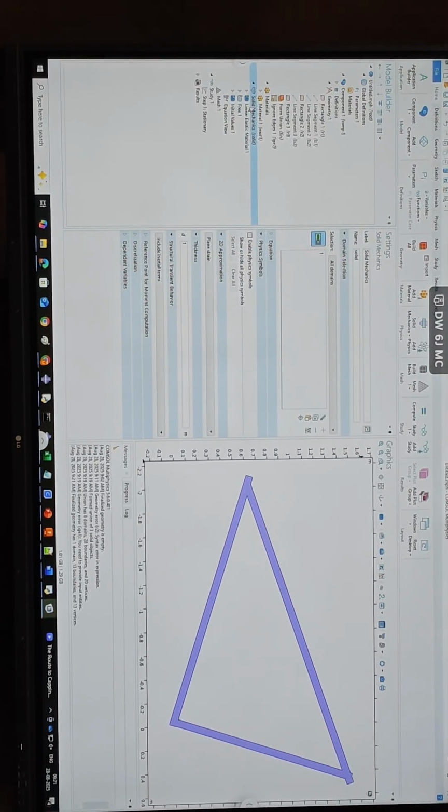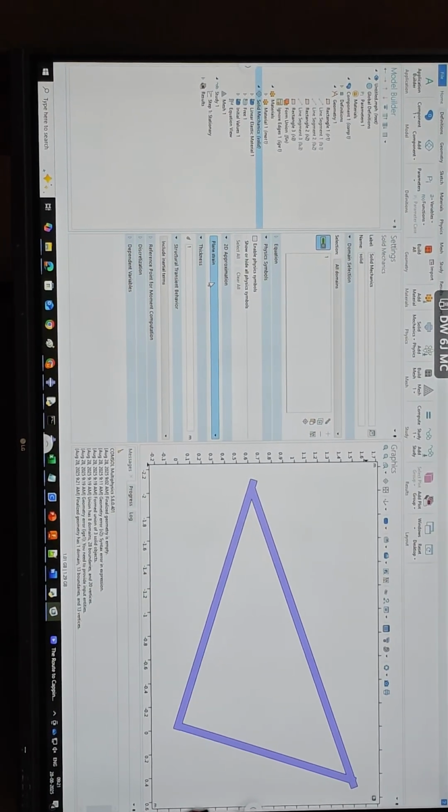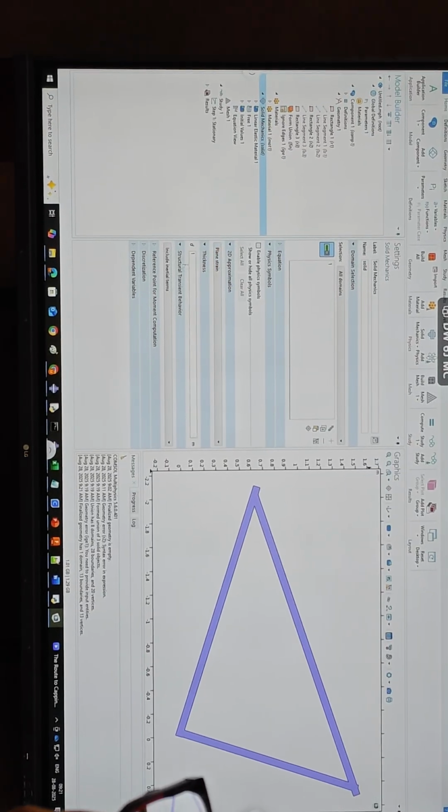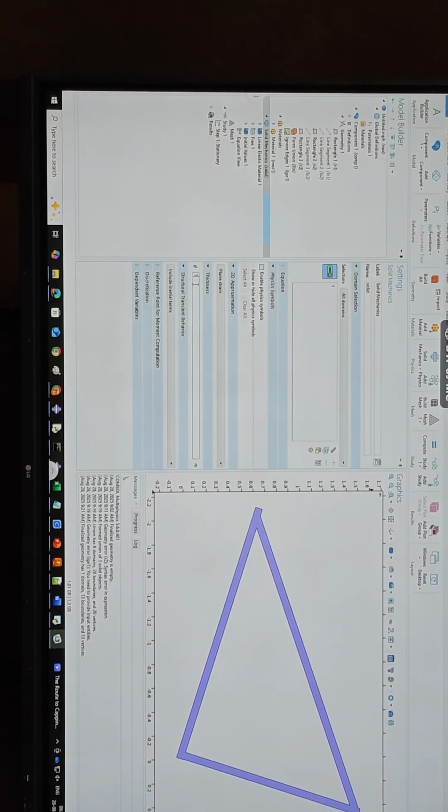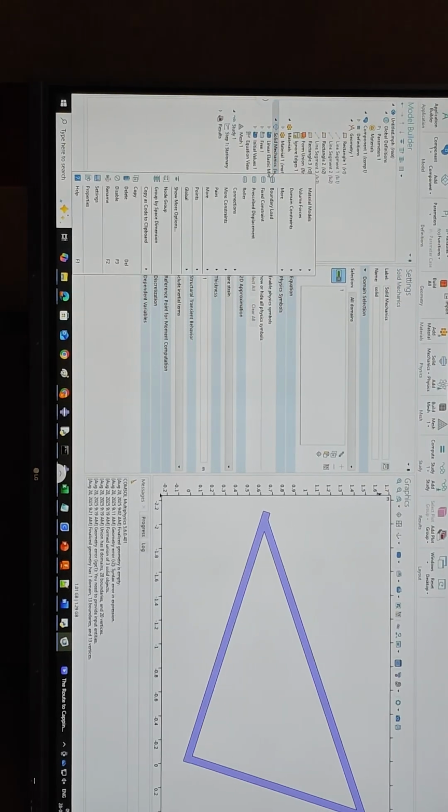Now you click solid mechanics, you see the type of model you're using here. So we are using a plane strain model. And here is where that out of plane thickness comes. So I've kept this as 1. So now if you multiply this with your B1, B2, you get your area of cross section. That's simple. Right? Now I right click solid mechanics.